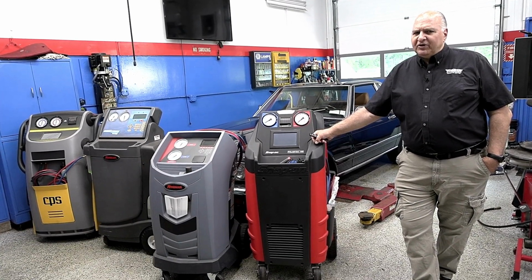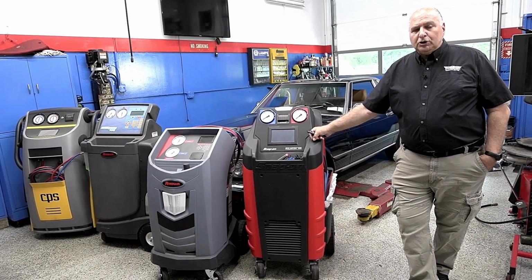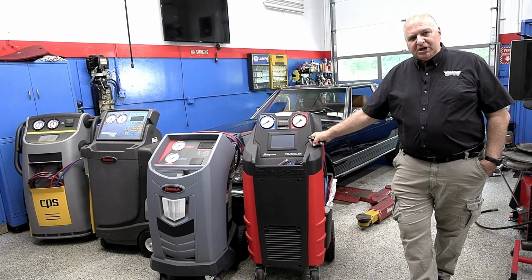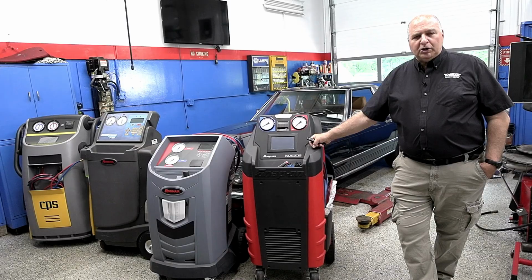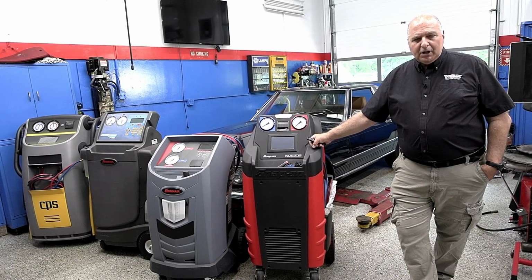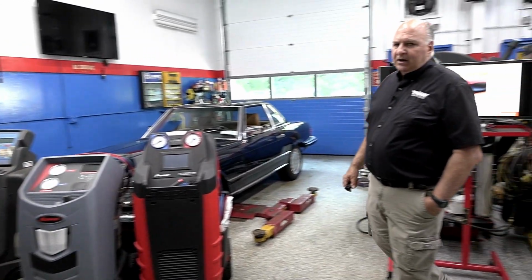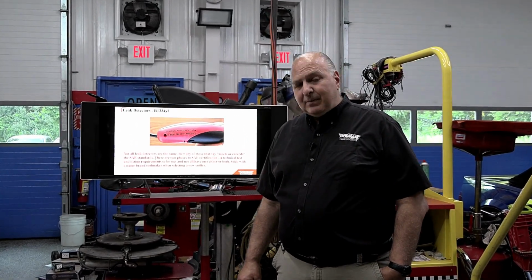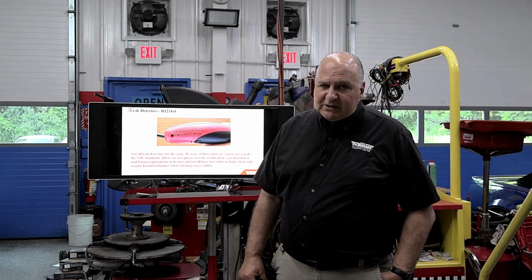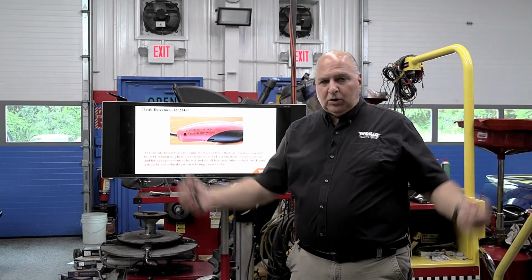Oh, but you wanted to fill it up. Well, guess what? Too bad, because the machine is under a J spec that says you can only put that amount in. The low side is always higher when the system is off. That's why they want to put the least amount in there. And since it's flammable and very expensive, they don't want it leaking all over the place.